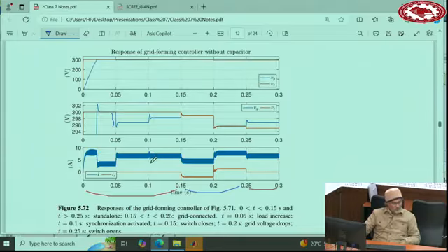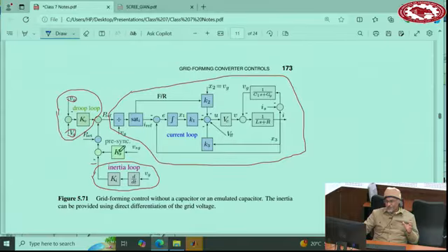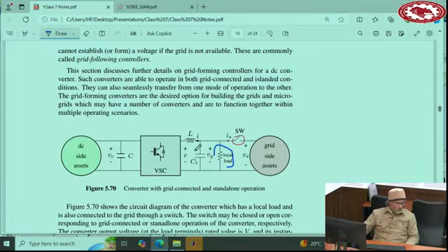The job of this synchronization term, and we have this concept very much in AC, which we discussed in more detail, is that it looks at this voltage and this voltage and the difference between the two, and brings the difference to the feedback loop. The feedback loop will push these two voltages close to each other, so now you can connect the grid switch.